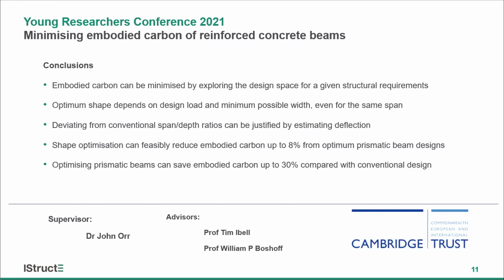That's really interesting. And just aware of time, the one burning question in my mind was, does the rebar take the shape you need, or do you have to bend it, or does it just sag to the right shape? There are two things about that. We can use steel reinforcement bent in that shape, but if it is challenging and if you are going for much more complex shapes, we can use flexible FRP bars. And I think in my group, Dr. Jono has worked on those things. We can use filament winding techniques and make bespoke reinforcement cages as well. So there are several options we can adopt for these kinds of construction techniques.